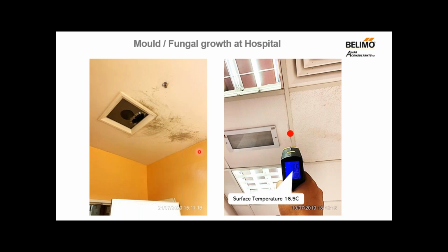The photo on the left shows a bad installation of duct connection to the diffuser. This is because there was insufficient turning radius for the flexible duct. Therefore, the duct lies on the ceiling and the air diffusion is not uniform coming out from the diffuser, resulting in colder temperature on one side of the ceiling surface.